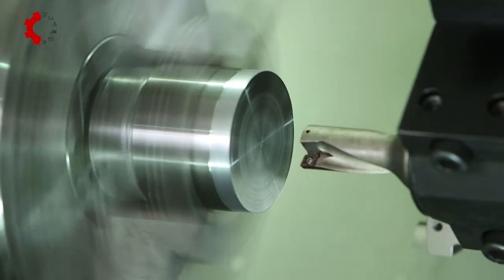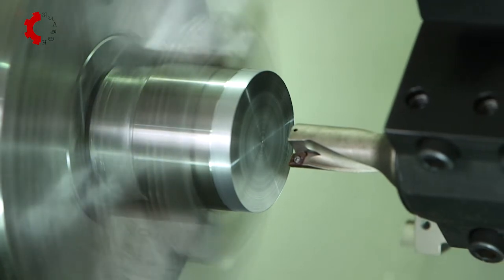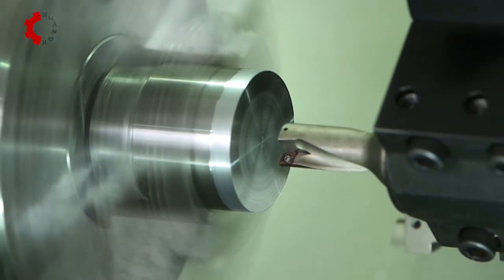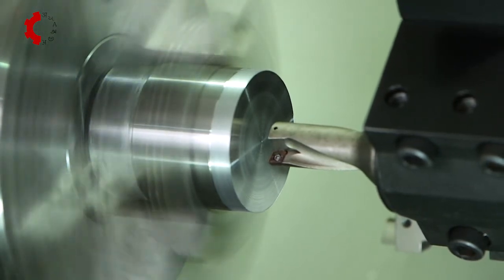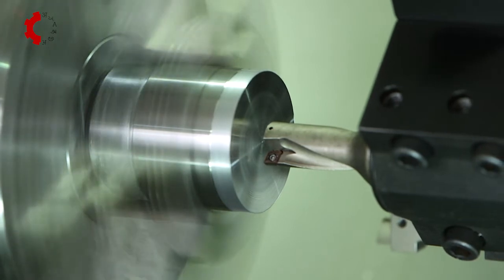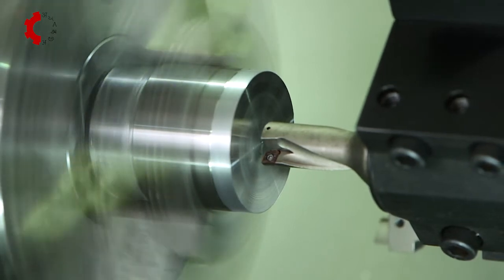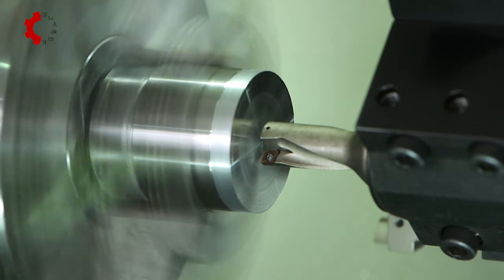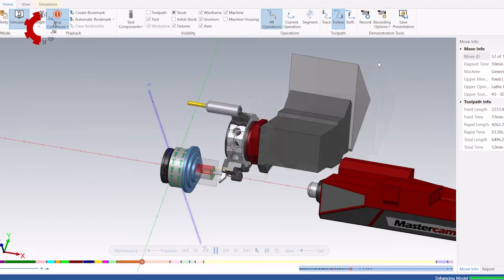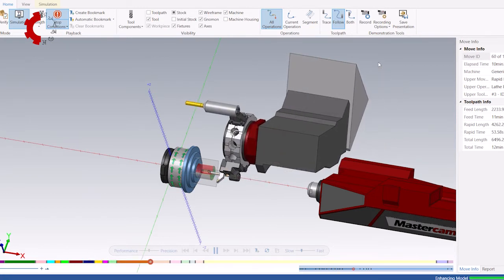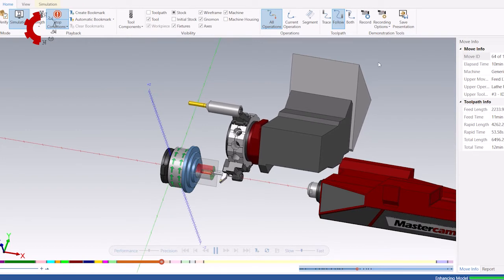Warning: sometimes drilling and boring is also done on CNC lathe. X offsets of boring tools cannot be taken before drilling. If you forget this and start executing boring program, the program will advance with the offset value in the memory taken for some earlier processed setup. There will be an incorrect offset which will create an accident as well as wrong jobs. Do not forget to take boring tools offset in X after drilling by interrupting the program.